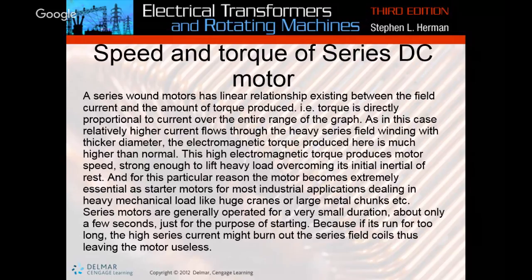For this particular reason, the motor becomes extremely essential as a starter motor for most industrial applications dealing in heavy mechanical loads like huge cranes or large metal chunks. Series motors are generally operated for a very short duration, only a few seconds, just for the purpose of starting, because if it's run too long, the high series current might burn out the series field coil, leaving the motor useless. Yes, sir. So you have a parallel motor then?